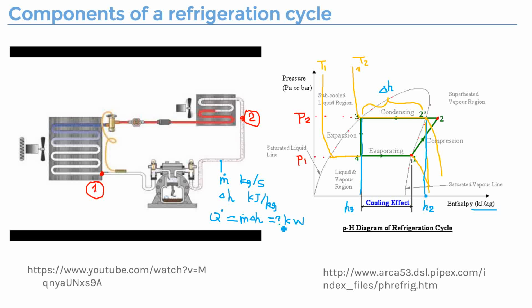And that amount of energy, like in different processes, you will know. For example, I just finished this cycle here. I just listed point 2 that's coming out of the compressor, so that's here. And then coming out of this condenser, point 3, is a process where we say there is no pressure change, because obviously there is nothing to cause a huge pressure friction to make it lose pressure.